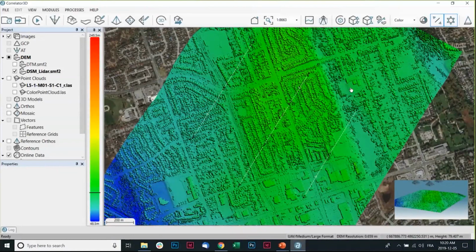Another thing that's important is if you want to ortho-rectify your images on your LiDAR DSM. I personally think that LiDAR is better suited for true ortho, since we have a sharper edge on buildings, and it usually gives much greater results if your aerial triangulation is well done according to your LiDAR system.